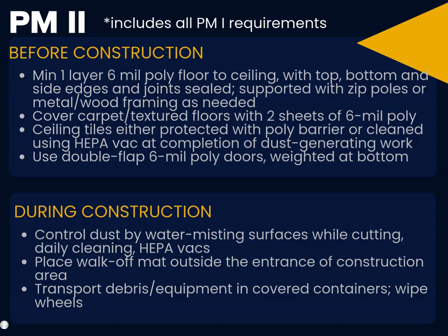Ceiling tiles are either protected with a poly barrier or cleaned with a HEPA vacuum once the dust generating work is done. During construction, dust is controlled by misting surfaces while cutting. A walk-off mat is placed outside the work area entrance, and any debris or dust is captured with a HEPA vac attachment. The area is cleaned daily using a HEPA vacuum or wet mop, and all debris and equipment are transported in covered containers with wheels wiped clean.